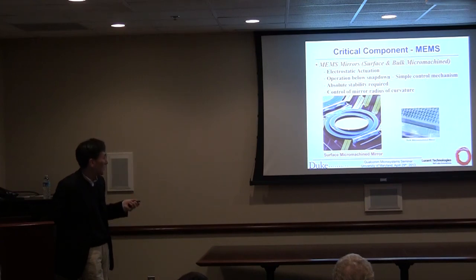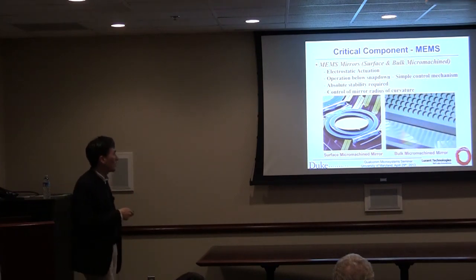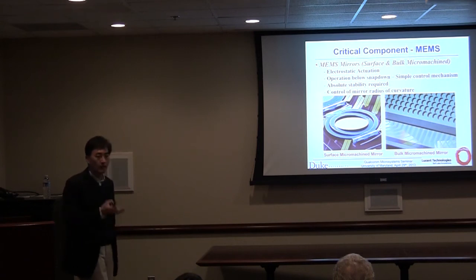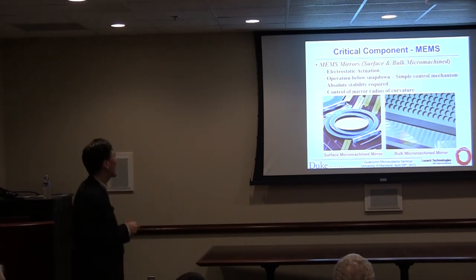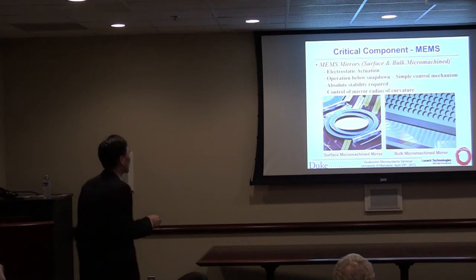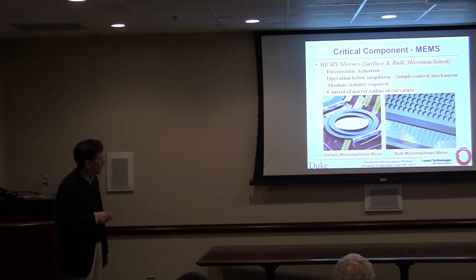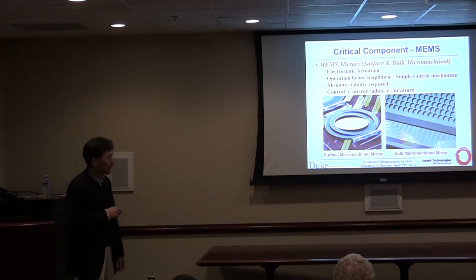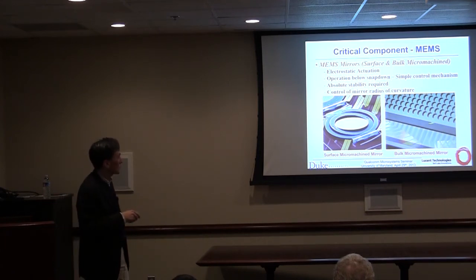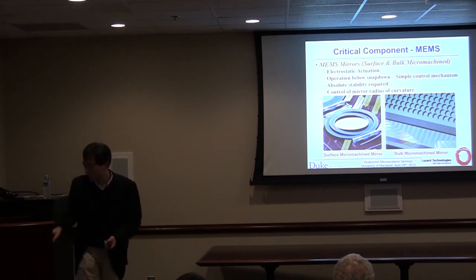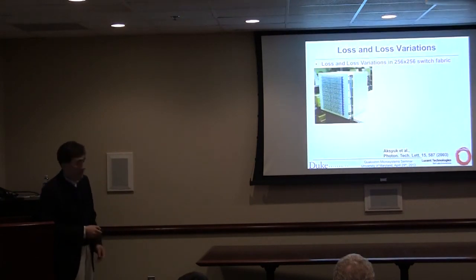We actually developed these MEMS mirrors. A lot of them were developed by my colleague Vladimir Aksyuk, who's now at NIST, went through University of Maryland. These devices were designed by my MEMS development colleagues, and we can make very large numbers of these mirrors. Here, using a surface micromachining technique, we've created 256 mirrors, and using bulk micromachining, we've created 1,296 mirrors. Then we can build optical switches that look like this.